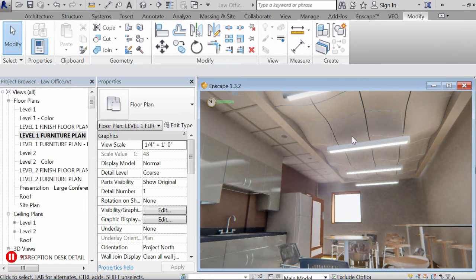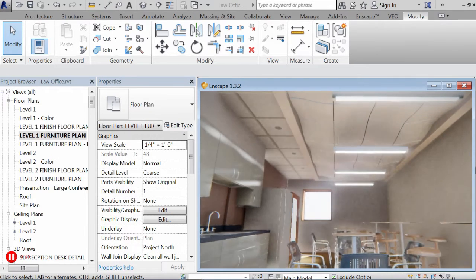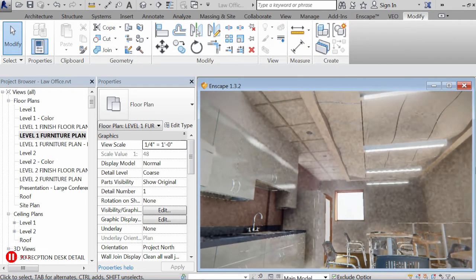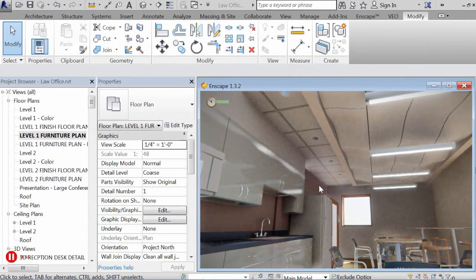Another interesting thing that is done here is there's a special wall type for the bulkhead. As you know, the bottom of walls do not get a material assigned to them. So this special wall type has a sweep defined across the bottom of the wall. What, just along the bottom edge? Is it just a very thin veneer, like the thickness of a finish? Yeah, so that's the thing. It's actually the same thickness as the gypsum board, and it's the same material. So when you're cutting your details through that, you'll also get the gypsum board across the bottom, which is how the detail should look.